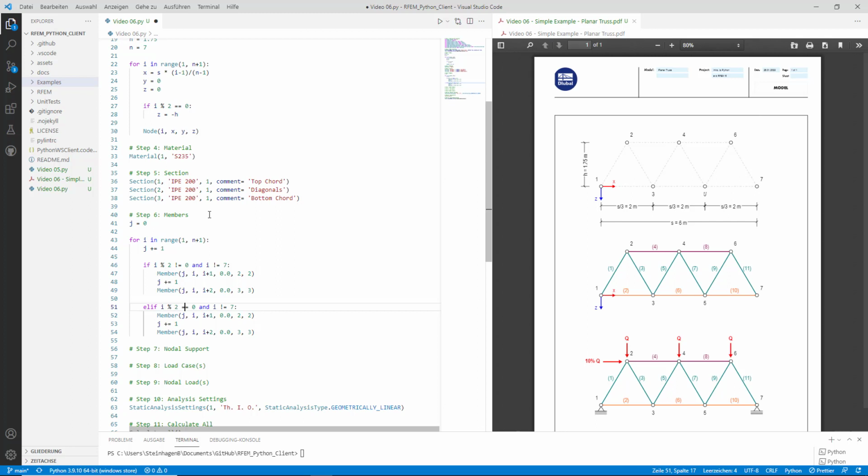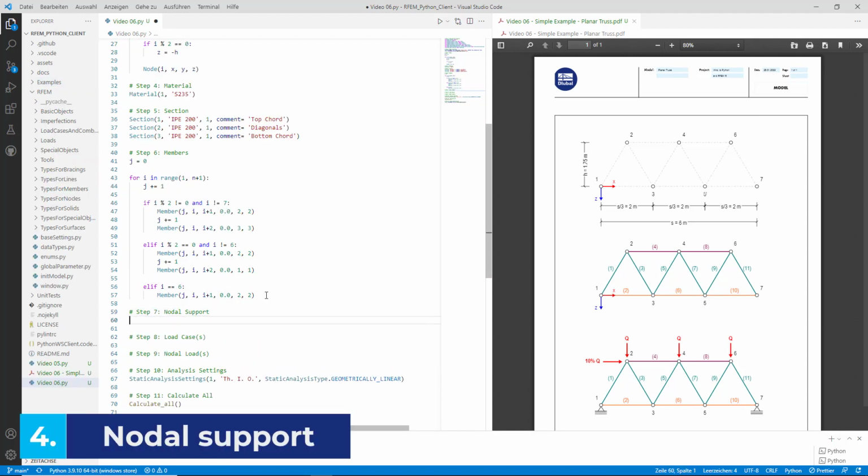Furthermore, we want the loop to ignore the final even number, which is 6. Because we ignored the final even node number, we still need to close this diagonal off. Here we can explicitly create a filter for that node number.